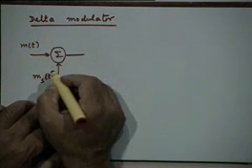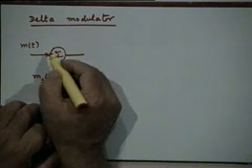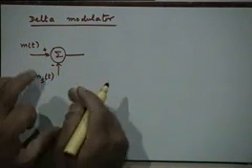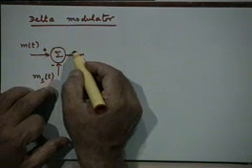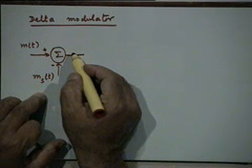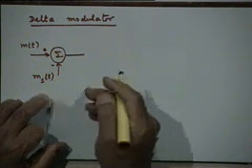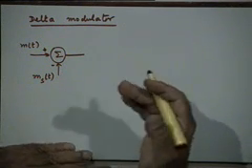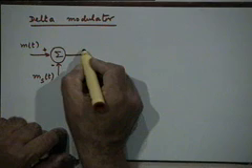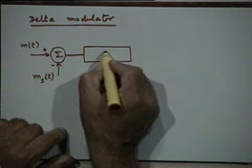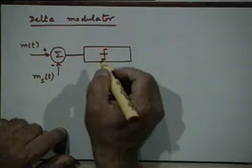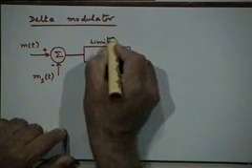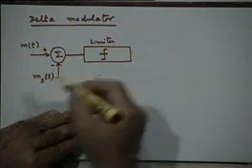So you look at these two signals. Basically, you have a comparator, you subtract these two. So what you get here is the difference between m(t) and m_st(t), right? If the difference is positive, you generate a positive output. If the difference is negative, you generate a negative output, and to do that you have to have a limiter. So we have an amplitude limiter, right, which clips the output. If it is a positive signal, it will make it a plus, let us say plus 5 volts or plus 10 volts or plus 15 volts, whatever fixed value, let us say plus 5 volts, and if it is a negative output, it will convert it into minus 5 volts.